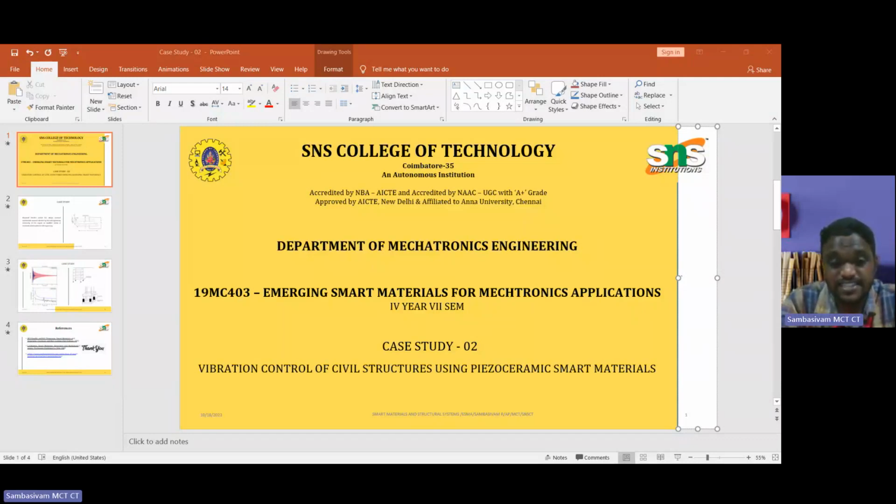They are used to identify the directions in the piezoelectric coefficients, with axes 1, 2, 3 corresponding to the X, Y, and Z axes. The polarization is set during the poling process, which induces the piezoelectric properties of the material by applying a large DC voltage to the element for a period of time. That axis is taken parallel to the poling direction.